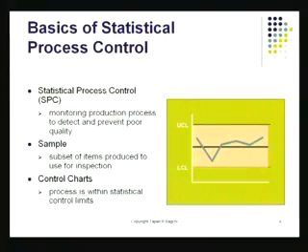What do we do here? We plot a chart and we compare the data to these control limits. The data I got was from this sample. And a sample is basically a representation of the production that is going on. The real production may produce thousands of these pens per day or perhaps even per hour. And perhaps every 15 minutes, I walk up to the machine, I collect a handful of those pens, they become my sample. These are the ones that I inspect 100%.